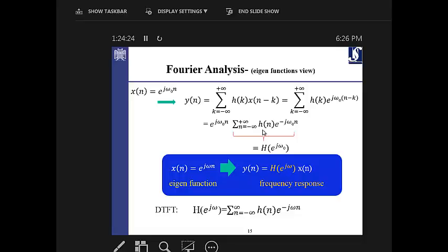In this case, we give such a function as an eigenfunction, which is the atom in the Fourier dictionary. So all the atoms in the Fourier dictionary can be generated from this just by defining different omega values, omega 1, omega 2, omega 3, and so on. You generate all the necessary atoms in the Fourier dictionary. Because all of them are the basis or the atoms, if you give them to this LSI system, the output would be the coefficient of that input.